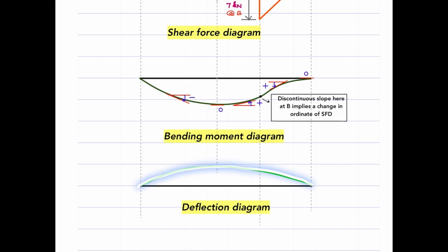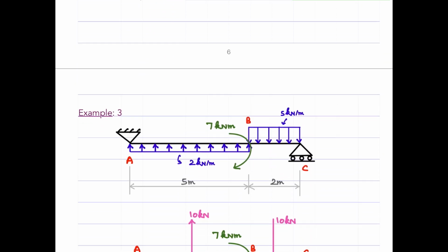Then with the same idea I explained in the last problem, one can show the reflected profile like this, right? Because the bending moment is throughout negative, right? Which means if the bending moment is negative, the curvature is negative. That means the profile should be opening downwards. Reflected profile should be opening downwards. Also see that here this is the tension side, this is the compression side, right? So we see that the bending moment is drawn below the neutral axis. Okay, that is the usual observation.